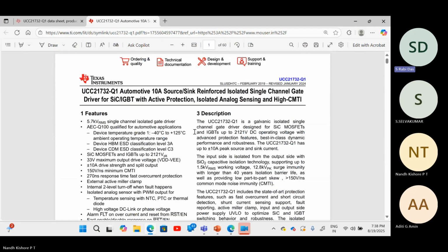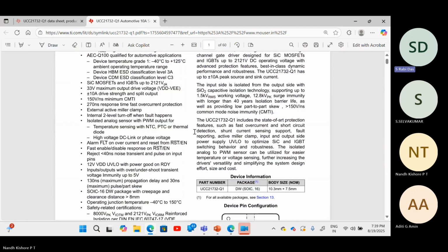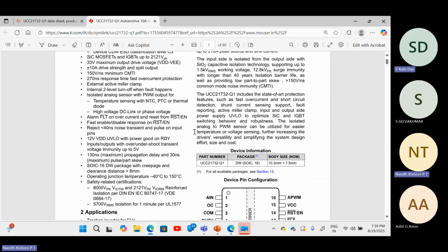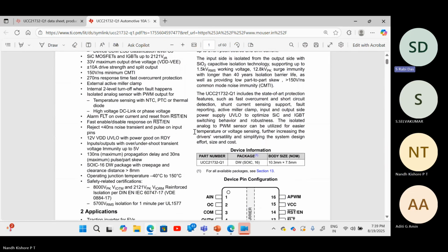Generally, some 100, 200 kilohertz only some data is given, but actually at what maximum switching frequency can it operate? First things first, I'm dead sure you will not be using SiC MOSFETs or IGBTs at 5 megahertz, right? Yes, GaN only, GaN MOSFET only.